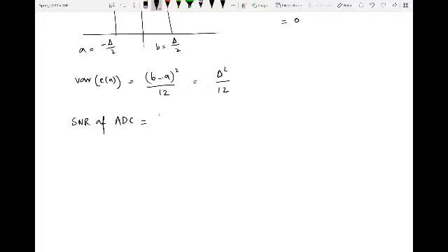So it will be power of signal divided by power of error, which is noise, because error is acting as noise. The power of signal is given by simply, let's say if the input signal was x, it will be simply x square by using a standard 50 ohm model, and the power of error is delta square over 12.